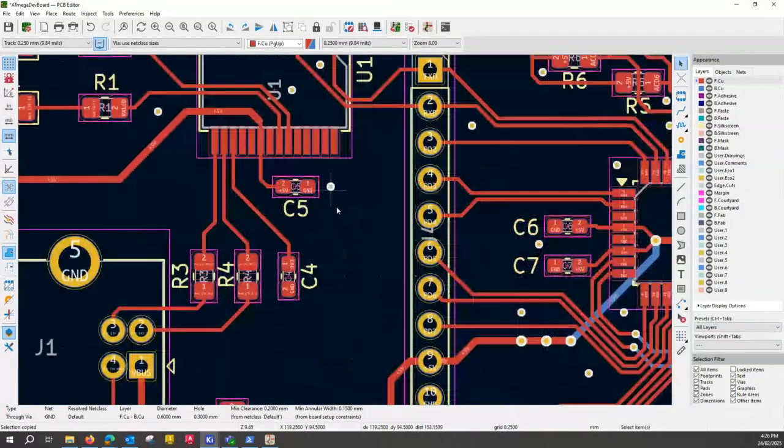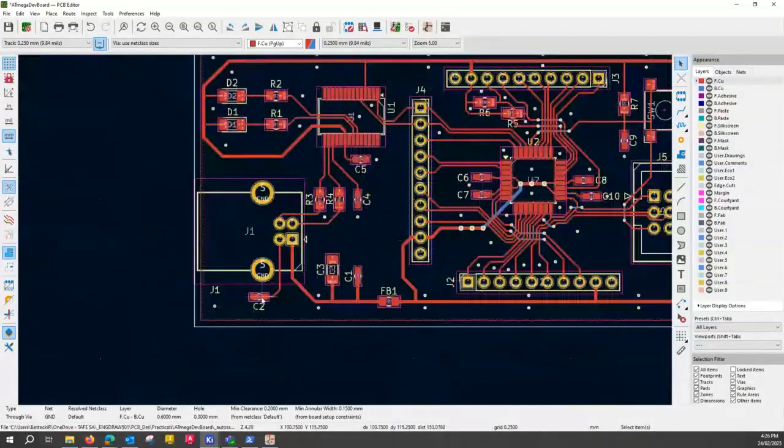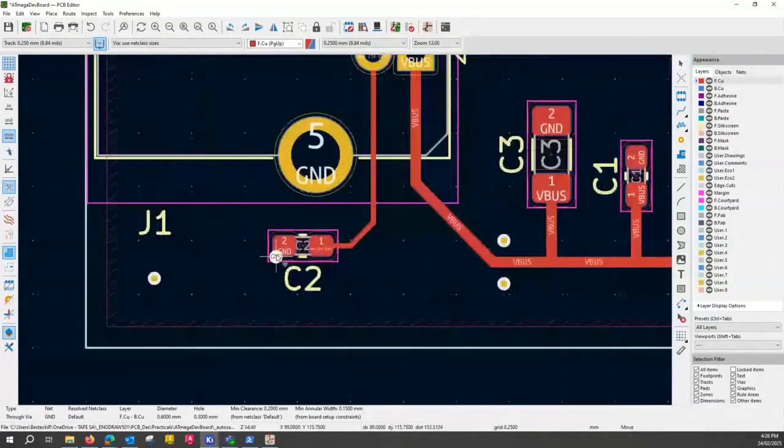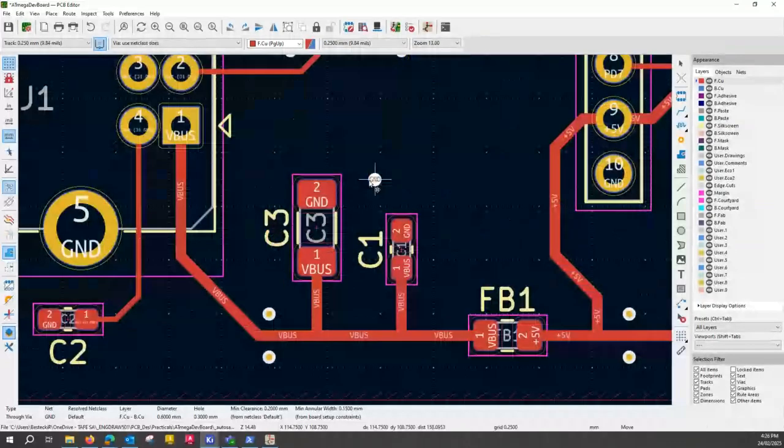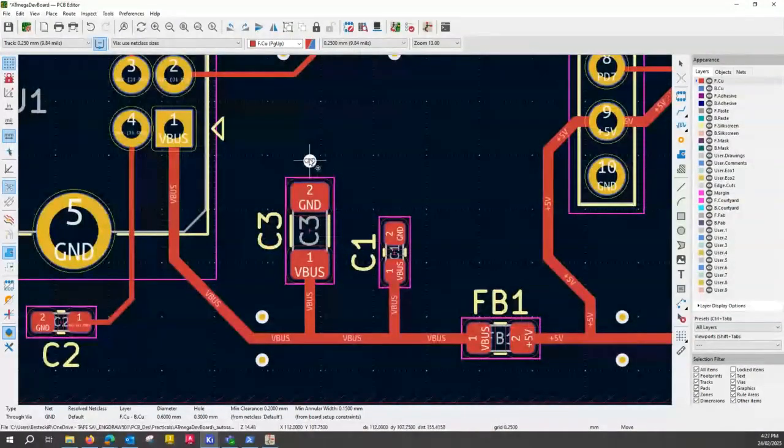Capacitor again. Capacitor again. Those areas, really okay. I need to include this internal area here, so I'll just put one here. And what else? We could put one here, but realistically, this is one big area with a big pin right there, so we don't need to. But we've got a couple of capacitors here, and I definitely want to stitch behind those two.